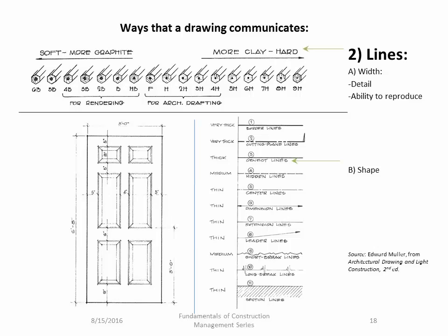Often what you'll see is architectural drafting uses anywhere from right in the middle of this scale, from an F to a 4H, 4H being the hard, or if you're going to be doing renderings and different colorings of the drawings, you'd start in the opposite direction to the left, start with an HB and go down to 4B, being some of the softest leads that you might use.